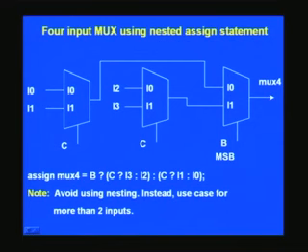So now we will make it a little more complex by going for a 4 input mux. Let us consider I0, I1, I2, I3 as the 4 inputs that you want, and naturally this calls for 2 selector pins. They are C and B, and note that the same C is used for both, and this one here happens to be the MSB. You should be clear which is MSB and LSB, because otherwise the whole thing will become chaotic, since the tool only treats it in that particular fashion.